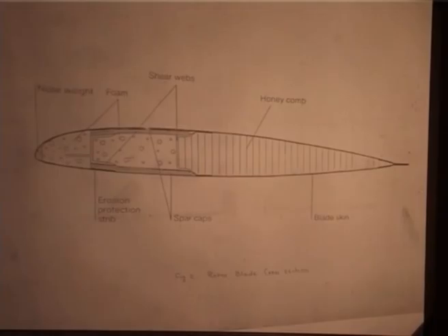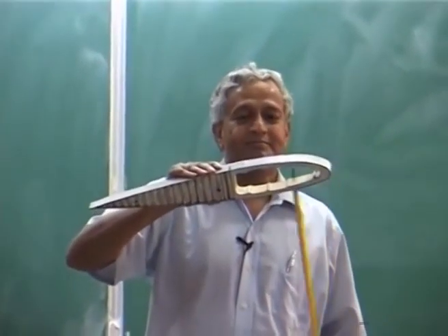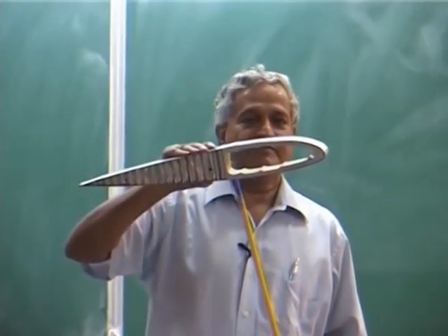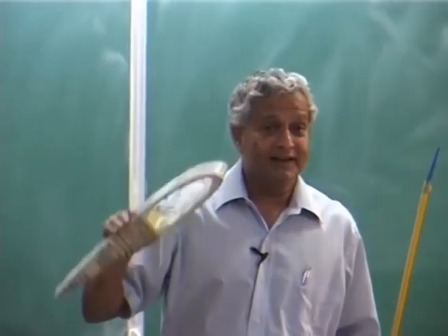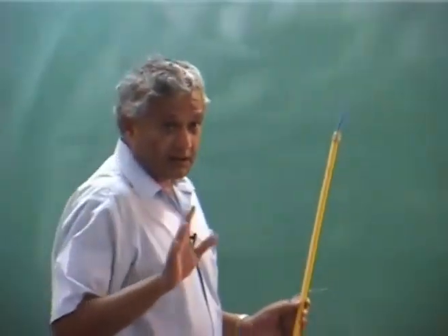That means the design of your cross section is very important, where you put this vertical member, this portion, so that this is your load carrying part. You can see where the shear center will be, and you try to keep it at 25%, but not all designs have to be like that.